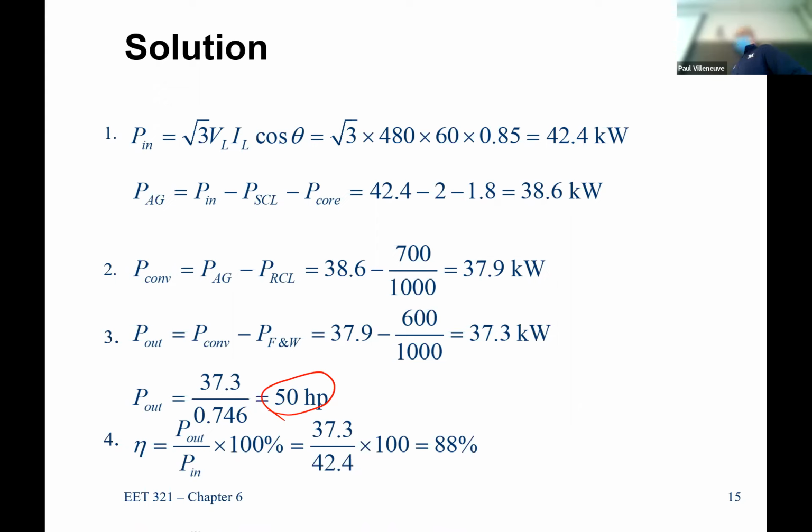Which is probably getting close to the theoretical limit. If you're talking about EVs and their motors, 92, 93% efficient is probably the typical for newer technology motors that you're finding. Which sounds like crap, but keep in mind, how does your reciprocating engine do? 15 to 30. A gas engine's probably 25, 27% efficiency, converting fuel to actual power to the wheels.